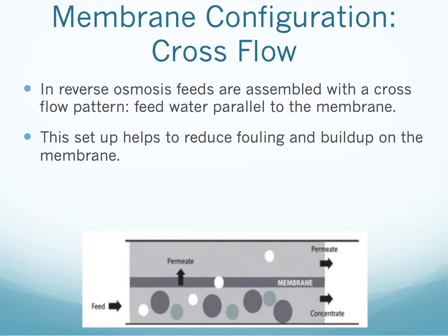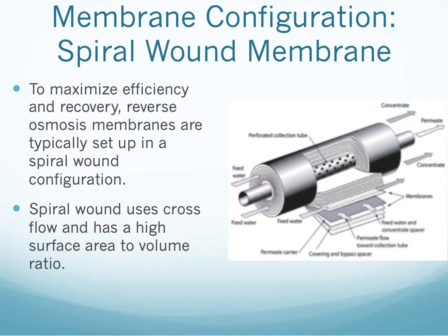flow pattern, and what this means is that feed water is run parallel to the membrane. This helps to reduce fouling and buildup on the membrane due to the velocity of the fluid passing by and it not allowing anything to attach to the membrane.